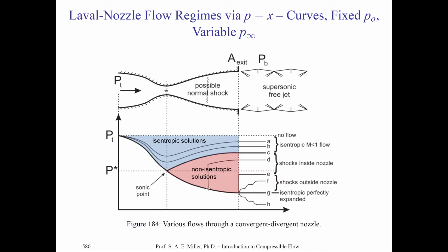In this case, part D, the shock wave occurs at this particular area ratio in the divergent part of the nozzle, and the pressure has a discontinuity and immediately rises, as pressure rises through shock waves, and then the flow will exhaust supersonically and pressure will continue to rise through until the nozzle exit and have subsonic flow. Indeed, we can push this shock wave all the way to point E. So if the nozzle pressure ratio pushes the shock to the nozzle exit, then we'll have subsonic flow outside the nozzle and supersonic flow completely inside the nozzle, and that's what case E is.